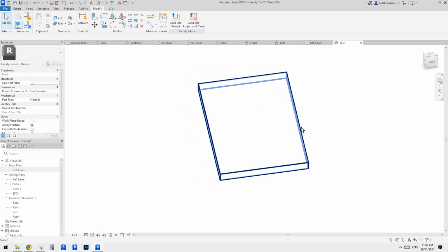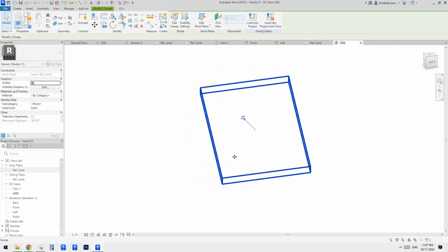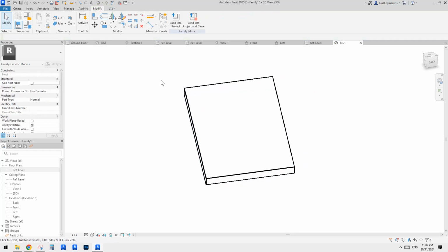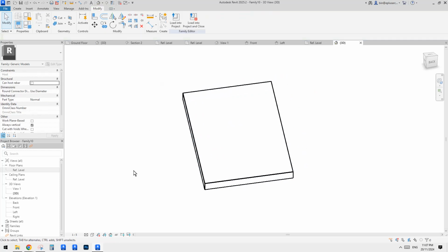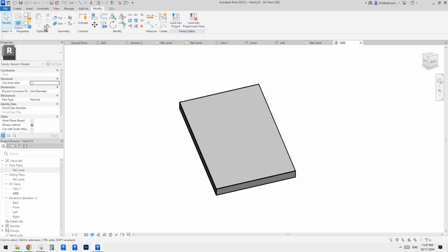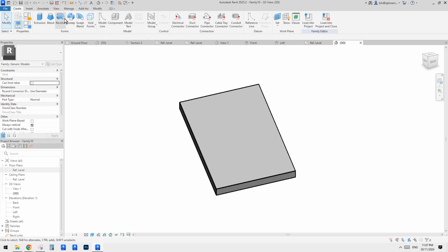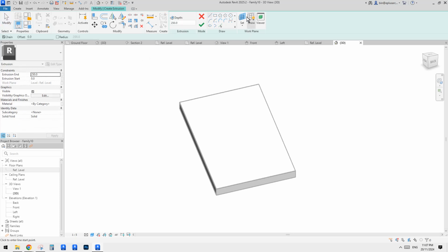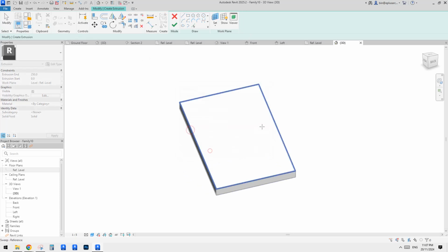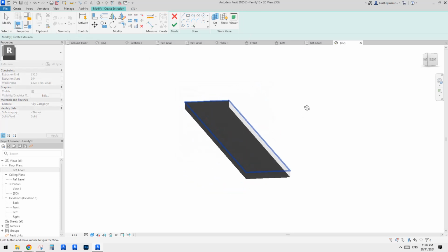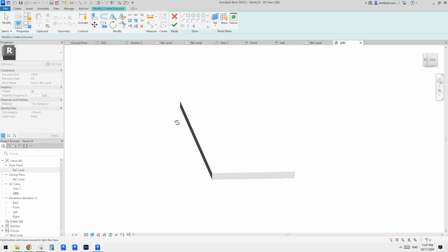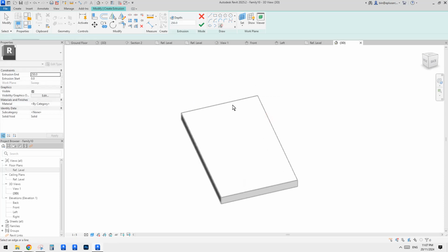I can. So for example, here, instead of having this solid and then try to cut corner, so hang on, let me change the graphic style. Yeah, that's better. So I would just try to create one extrusion and then set work plane onto this face, maybe this face, and then I'll just pick tab, pick all these, and then use fillet arc. I'll just try, I'm not sure, 100.